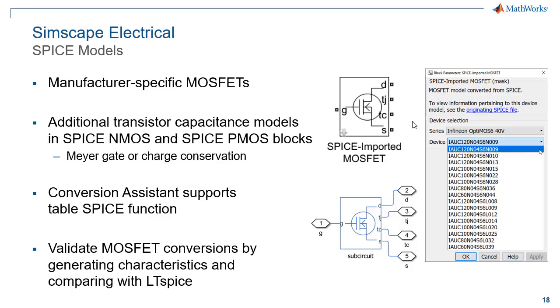This is a repeatable workflow for you as well. So we provided conversion assistance. And of course, then you can validate this conversion by generating the characteristics and comparing with LTspice.